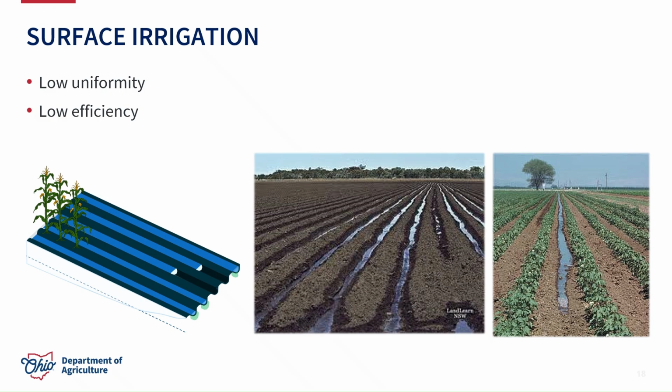For example, these furrow irrigation rows may have some soil that was shifted around during planting or during spraying or during some wind blowing it around, causing the water paths to not flow quite evenly or be a little different slope, and that's going to impact how that water is distributed throughout that field. And as it's distributed less uniformly, you may have to over irrigate in certain situations to provide enough water to all of the crops, and that's going to reduce the efficiency of the water being used in that field.